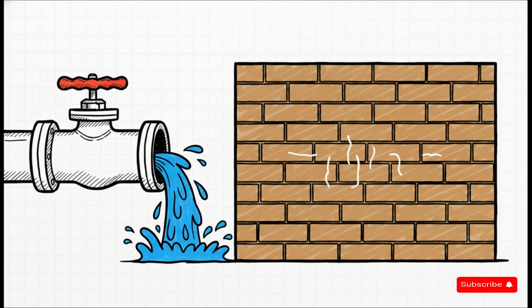And if that wasn't enough, then we have GIDL. That stands for gate-induced drain leakage. Because the electric fields are so incredibly intense in these tiny microscopic spaces, electrons actually tunnel right through the barriers. We are talking literal band-to-band tunneling here. It's crazy. These leakage issues became such a nightmare that they basically forced engineers to stop shrinking things flat on a surface and find a radical new way forward.